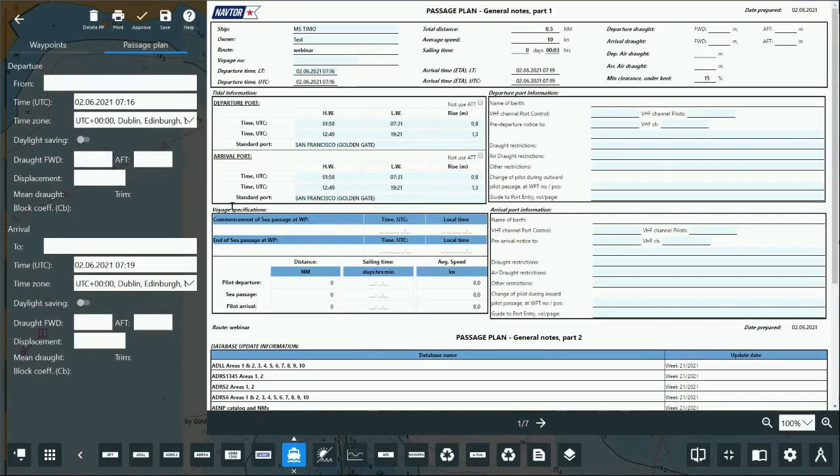How does this work? Why does it require 2 entries? If you have, for example, an ocean transit arriving with a different displacement in different densities, having an effect due to consumption, it will take it for the waypoint. If you have a number of 100 waypoints and you do that waypoint 50, it takes the delta between the departure and arrival displacement, and then sees how many nautical miles of the total distance has been made good, and predicts the displacement. It's still conservative because it basically takes these into consideration.